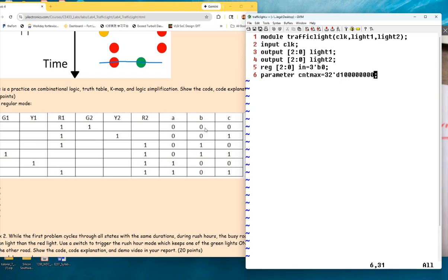And I think these are all the variables we need to declare. So we need a count. Count as well, yes, you're right. So count will be, let's directly follow the first one. It's going to be a reg, and how many bits? 32. And count, by default, should start from 0. All right. What's next?